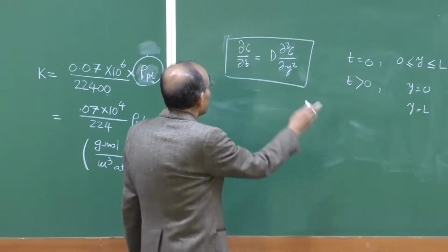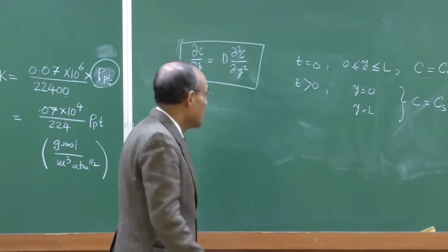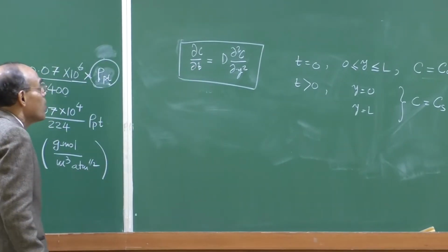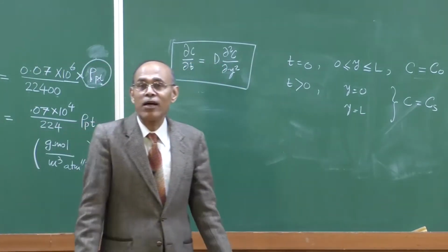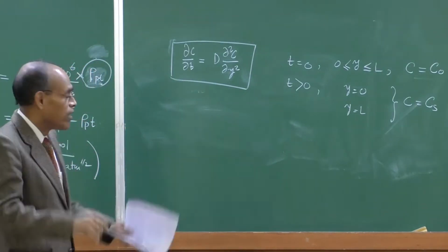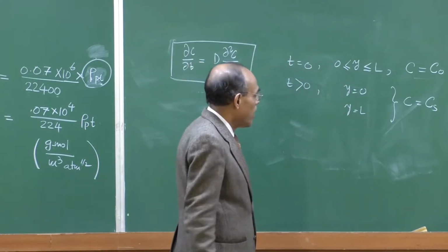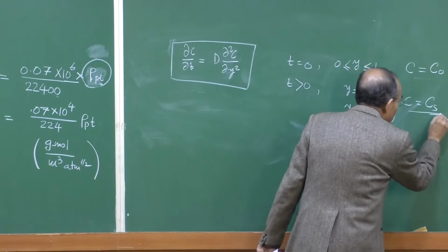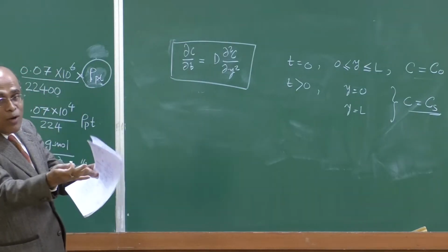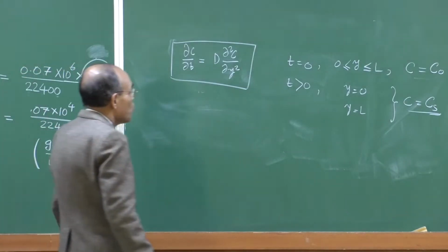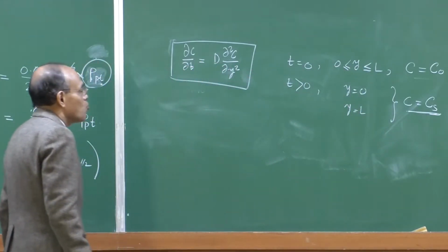Since we are trying to calculate the rate of diffusion, it essentially turns out the rates of other processes are infinitely fast or they are operating close to equilibrium. So, the chemical reactions associated with the diffusion process or the phenomena under consideration can be assumed to be at equilibrium, and it is based on that I have given an extensive lecture on this in my iron and steel making as well as transport phenomena, that the surface concentration is assumed to be fixed, where the solid carbon gets into dissolved carbon and that reaction is assumed to be at equilibrium, and you can find out from thermodynamics what should be the surface concentration, given the temperature and pressure.